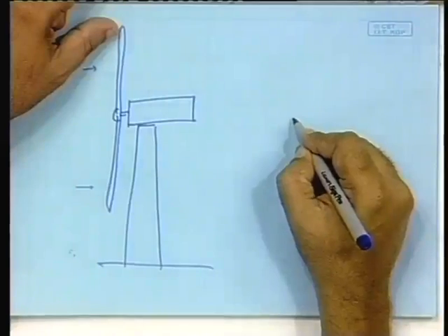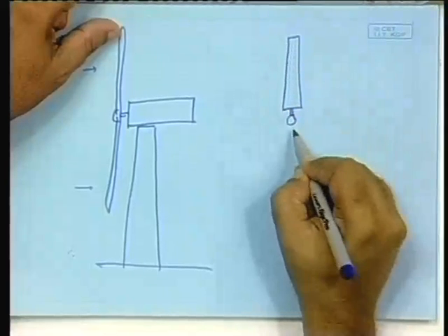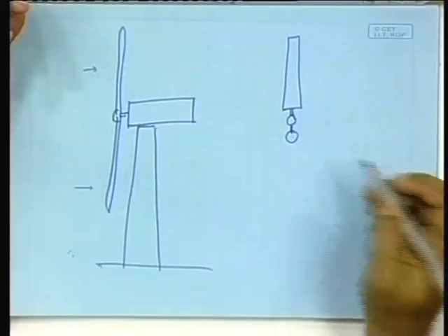That is why, even though economics works against it, many companies choose 3-bladed turbines. We will later see that there are advantages of going for even higher speeds, very high speed rotors. In that case, you might argue that why not one blade? Well, there have been rotors constructed with one blade. That means, I am showing the frontal view, it is just one blade, and the other side has to be balanced. So, there is a counterweight, that is all.